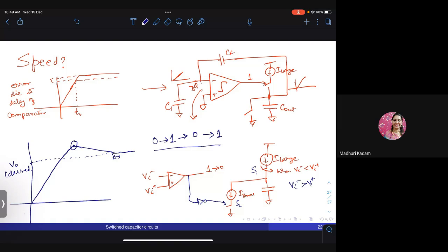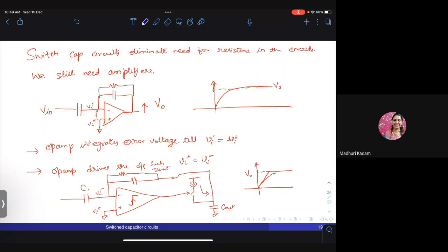So it's a very simple circuit once you understand it, but I think it's a very smart idea, of using comparators rather than op amps. The key difference here is that in an op amp, you are forcing the virtual ground. In a comparator, you are detecting the virtual ground condition being reached. It's always more power efficient to detect a condition rather than force a condition.